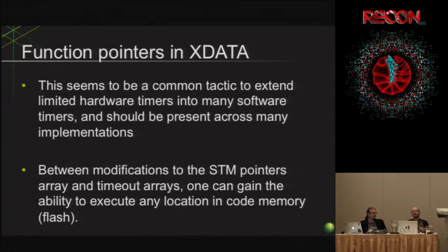Doing it this way, there are real-life considerations that make it really painful though. When I was doing exploitation and trying to write all this stuff, it was really painful. Even if you shorten the window, you control all these things, right? So you can shorten the number of cycles that it's looking for. You can say, I want you to execute every cycle or whatever, and then it'll execute on the next hardware timer interrupt, whenever that fires. But even then, with the Keil compiler at least, it's storing lots of stuff in Xdata right on top of each other.